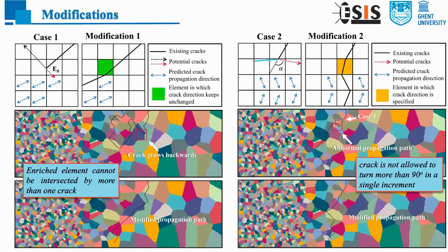During our simulation, we found some wrong results, in which the crack will propagate backward. Suppose there is a crack at the edge or the surface, and we apply the tensile load on the two sides. So we know the crack will propagate to the other side. There's definitely no chance for the crack to propagate back. So this is incorrect. So how did this happen?